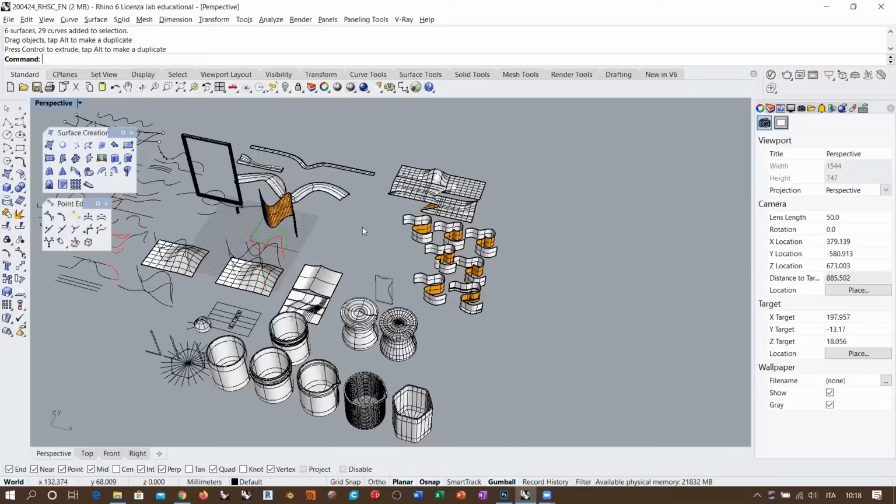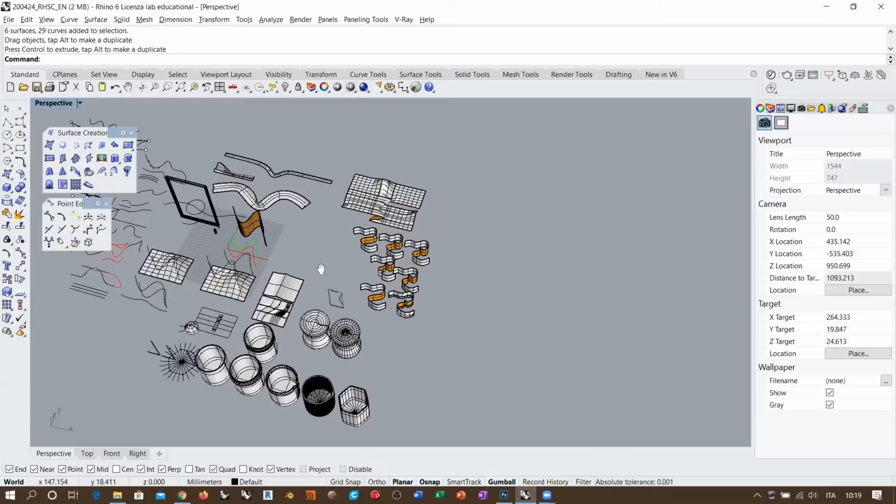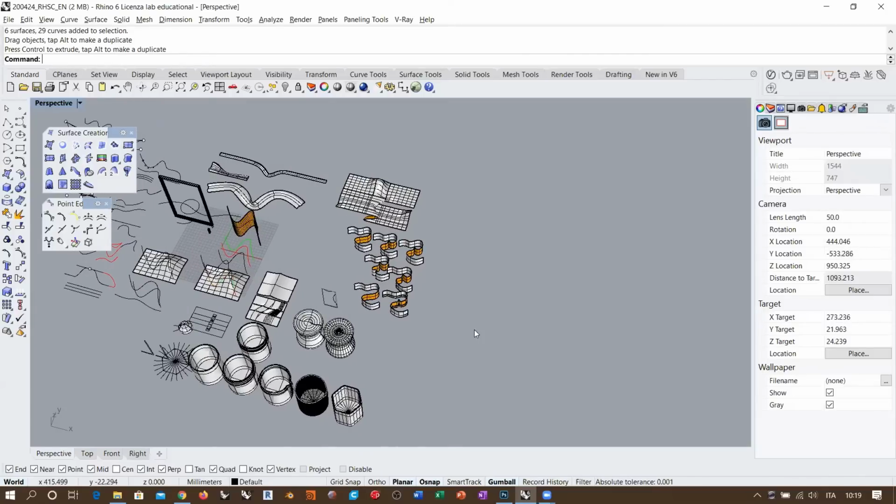Okay, so either you are at the end of the modeling workflow, or you have no other surface creation method available in that particular situation. Okay, and these two objects are the surface from network of curves and the patch surface. Now, I see daily that many Rhino users tend to use the surface from network of curves in order to solve almost any problem or to create any surface.